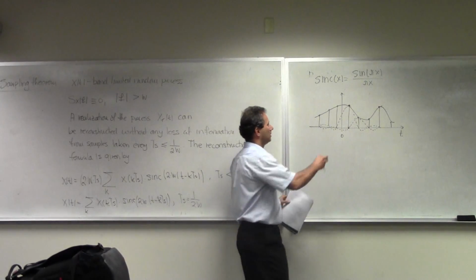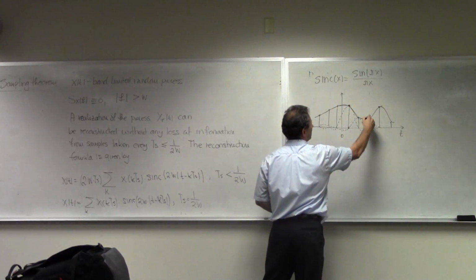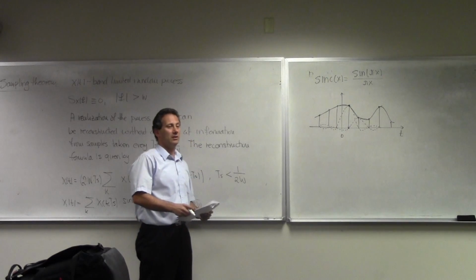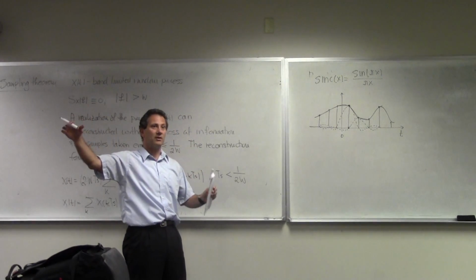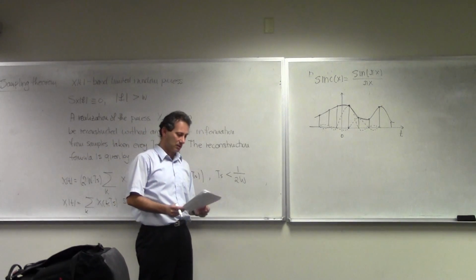And we might as well, in some applications, do this, and then deal with the consequences that we have some sort of distortion. Luckily for us, most of the time this distortion is going to be in a higher frequency, so we're going to low-pass everything after we do reconstruction and get our signal.